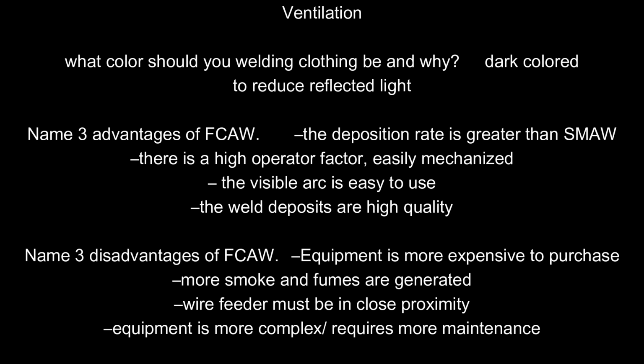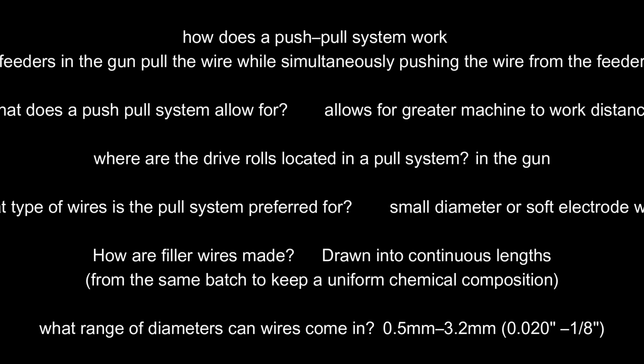Name 3 disadvantages of FCAW. Equipment is more expensive to purchase. More smoke and fumes are generated. Wire feeder must be in close proximity. Equipment is more complex/requires more maintenance.